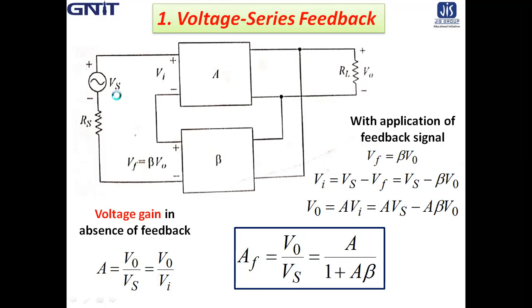In this type of feedback topology, a part of the output voltage V0 is sampled through the feedback network, which is connected in series with the input voltage Vs. Therefore, the voltage gain of the basic amplifier in the absence of feedback, that is Vf equal to 0, is given by A equal to V0 by Vs. In the absence of feedback, Vs and Vi are the same, so it can be written as A equal to V0 by Vi.